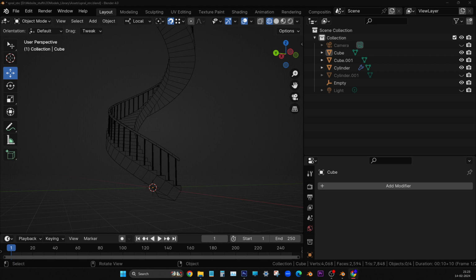So that is why, you messaged me that the cube is not so well connected in my file. That is space. So in the beginning itself, we should zoom and try to align so exact. It takes time, of course. Now just by typing 0.05, it'll get merged.